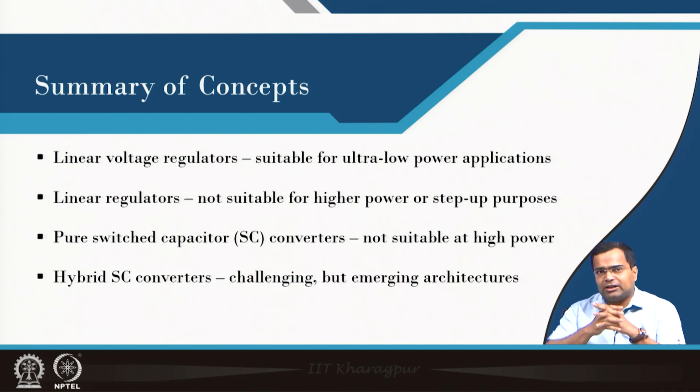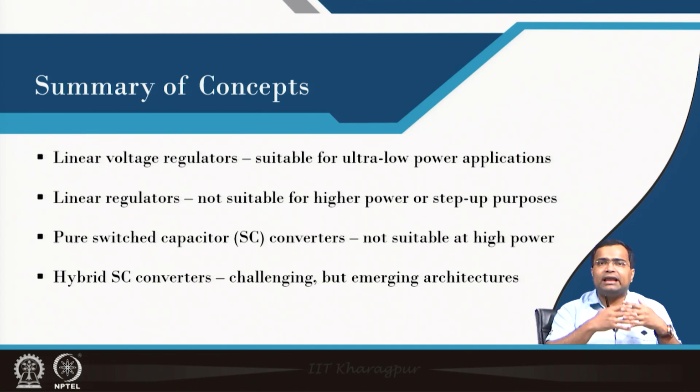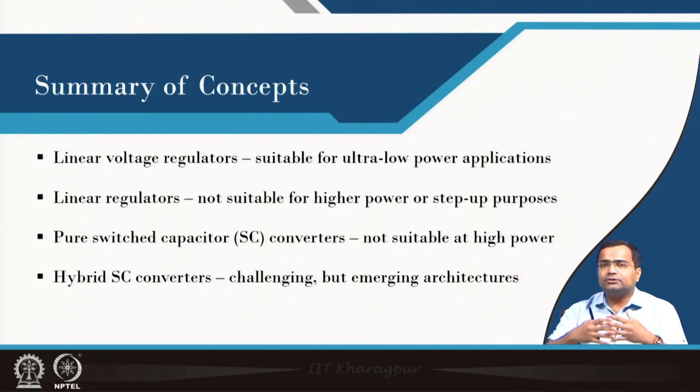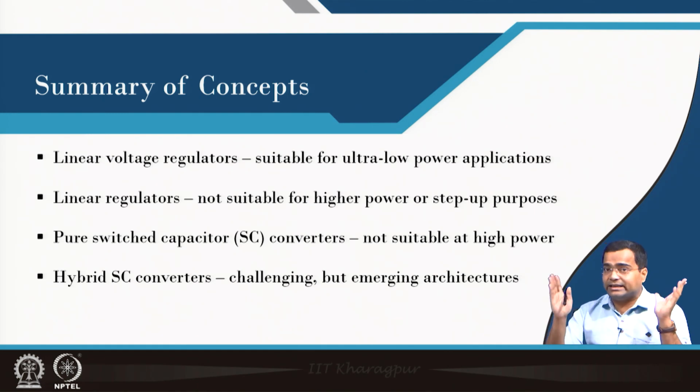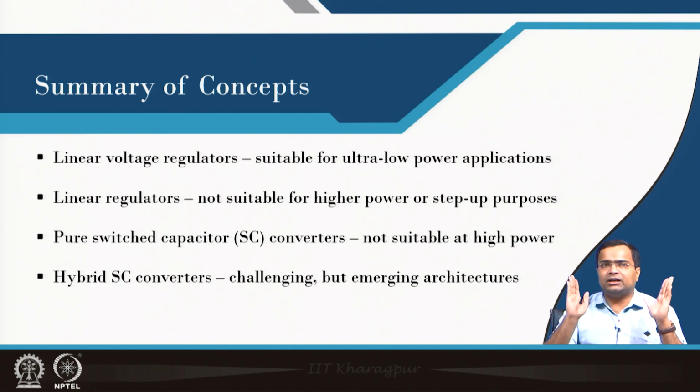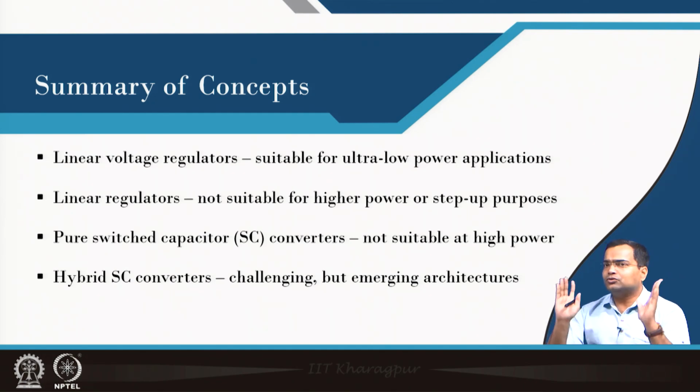And the hybrid switch capacitor converter, where along with the flying capacitor we consider a smaller inductance, is gaining a lot of attention nowadays for high frequency, high power density switch mode power converters, where we can design a much smaller power supply. This is an emerging area of research. But still there are a lot of aspects like optimization, modulation, and voltage balancing that need to be addressed.